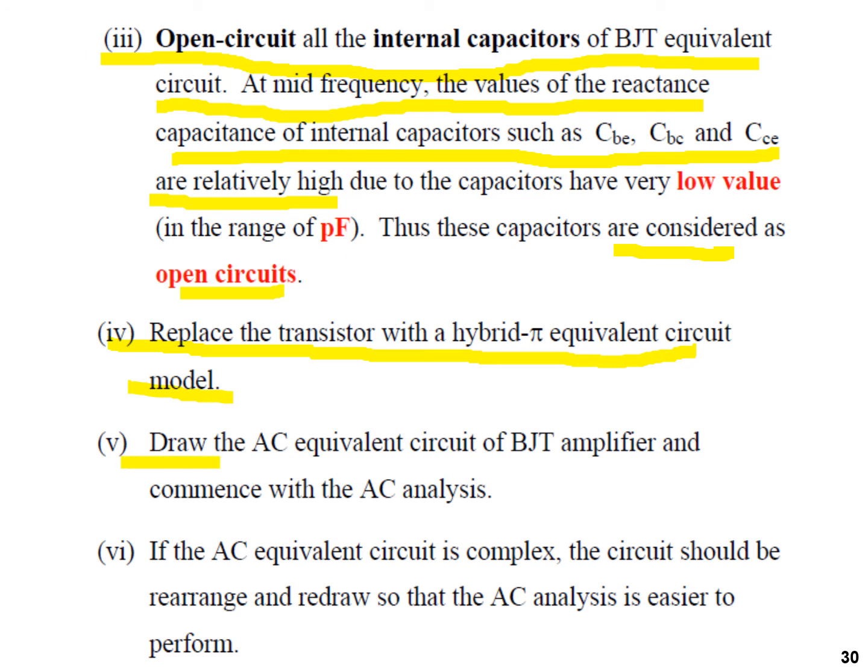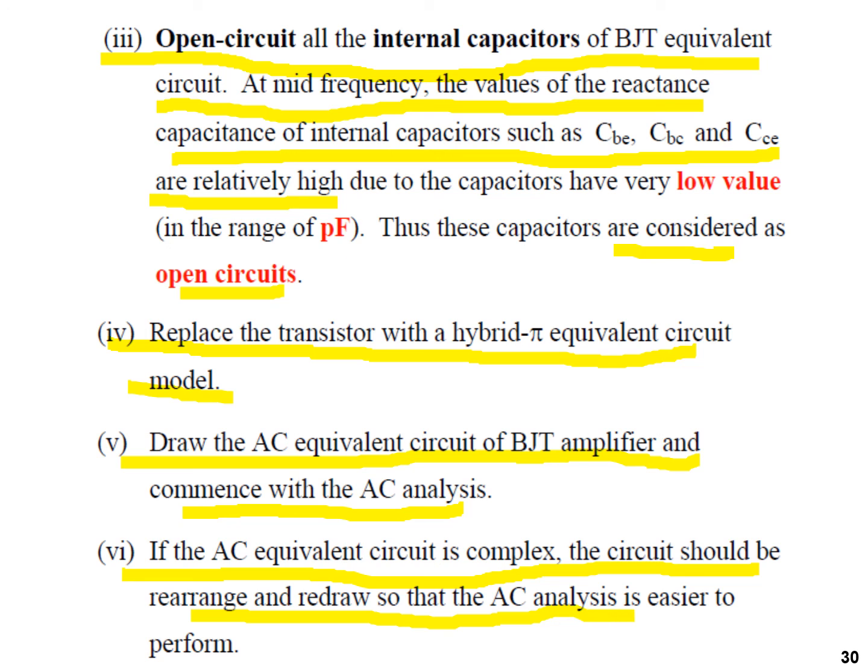Fifth, draw the AC equivalent circuit of the BJT amplifier and commence with the AC analysis. Number six, if the AC equivalent circuit is complex, the circuit should be rearranged and redrawn so that the AC analysis is easier to perform.